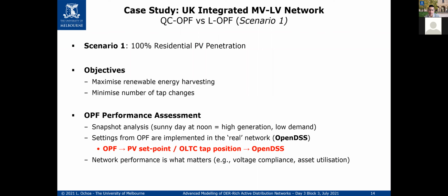But dynamic aspects are not relevant to distribution networks in general, particularly the moment that we get into the low voltages and mid voltages, and we're looking at connection of electric vehicles or photovoltaics. It's not something that distribution companies deal with. Now, the moment that we're talking about dynamics, because of the higher distribution level, for instance 66 kV, and we're talking about a solar PV farm or a wind farm, and you need to comply with certain requirements that involve dynamics, then yes, it is important. So it depends again on the DER that we're talking about. For a small DER, dynamics are really not that significant, to be honest, to the distribution company.